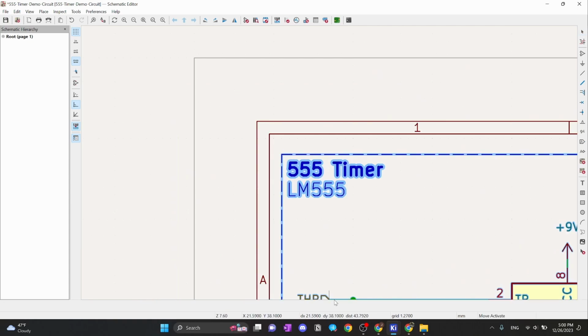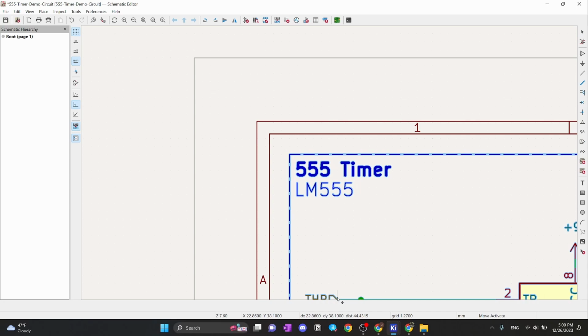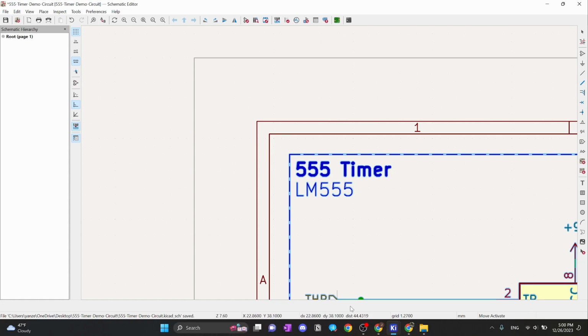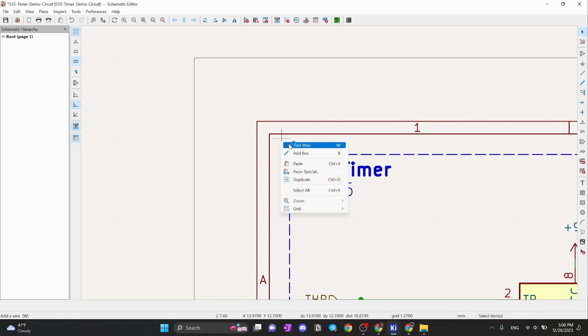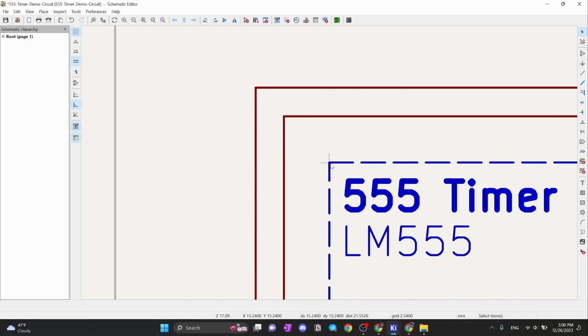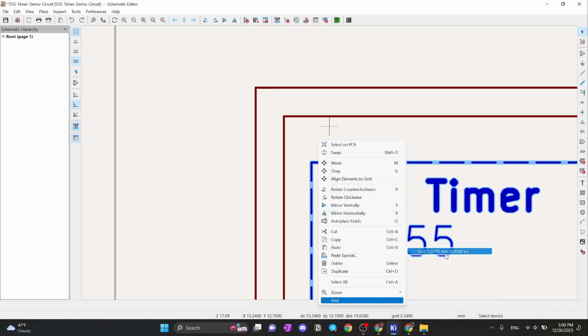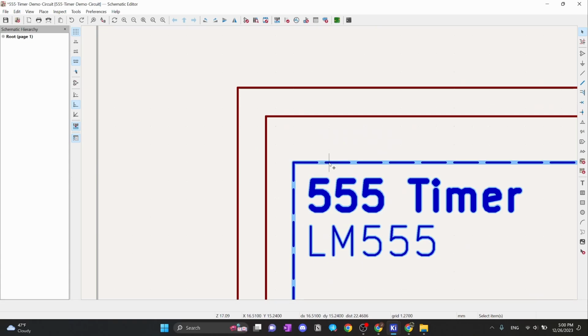And just move it ever so slightly. I think that's not going to align us with the largest grid, but let's see. Yep, that does align us with the largest grid. So basically you can do a quick calculation: if the left side is a little off from the top side, as you can see the distance is smaller, you can just go to the next lowest grid and move everything one grid to the right.